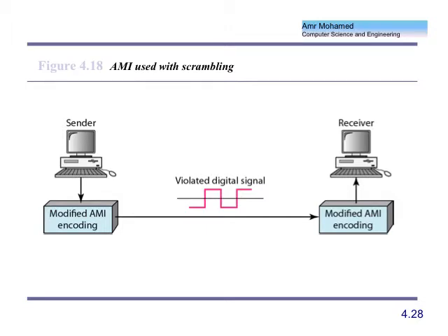It seems to be attractive from the DC component point of view, because as we said, for 0, we interpret it as 0 voltage. So the power consumption in that case is 0. So the power level for the low frequency component is 0, right? Which is attractive. However, this consecutive 0 pattern creates some kind of problem with the synchronization.